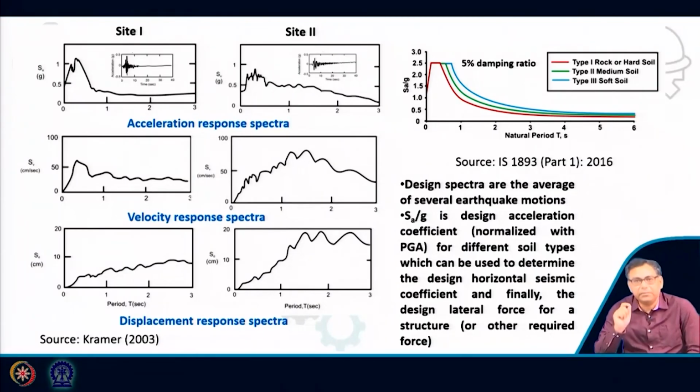For a given time period of the structure, you apply the same base motion, and you will get the displacement of that structure, and from there the maximum displacement for that corresponding time period.